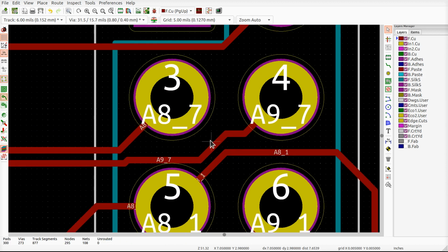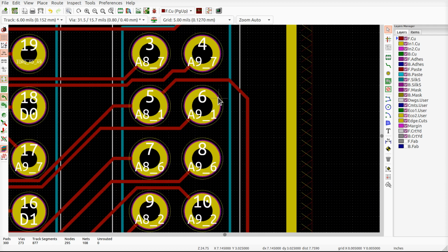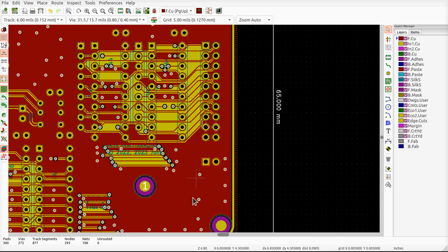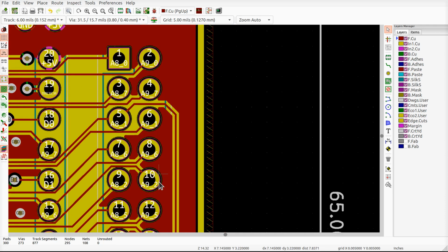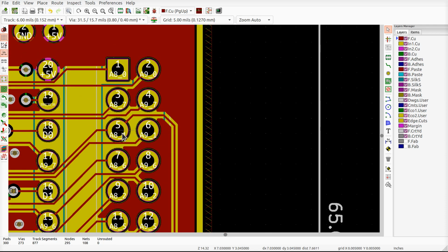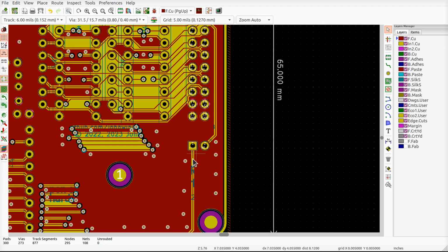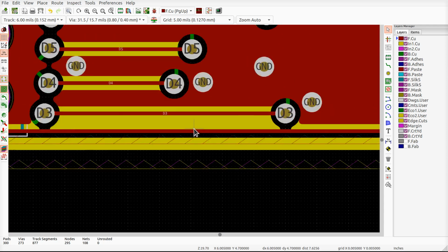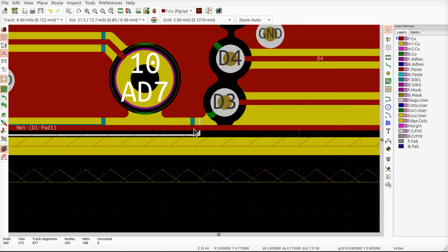I'm going to go ahead and do this, get rid of it. Oh, this is a kind of gnarly looking mess over there. That's okay. There's no reason for these to be rammed up right next to each other. All right, so we're looking pretty good. Turned on the fills again. Now, you can't see it and everything's shorted out, so I hit B to re-pour the polygon. All right, we can see the ground float around it quite nicely. It's up inside there. It's all looking pretty good. Pretty hunky-dory. All right, it comes out and around down here. These are kind of close, but not too bad.